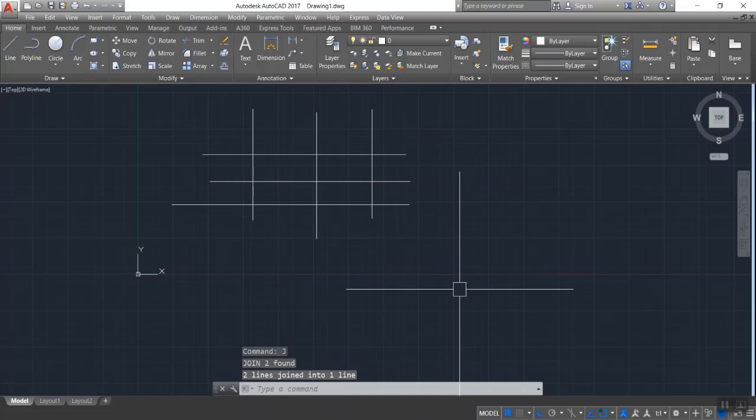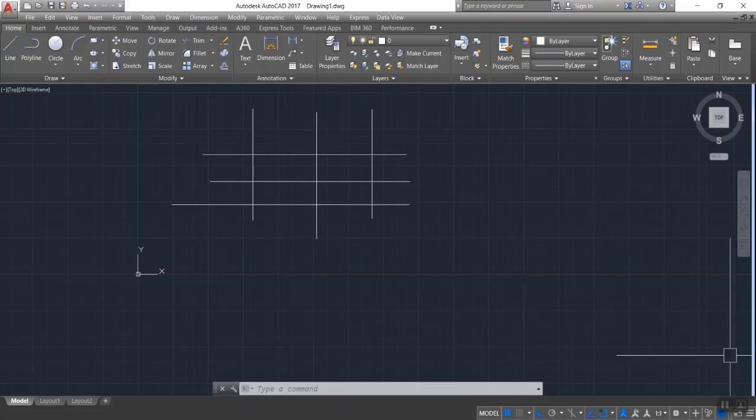It doesn't always have to be trimmed. If there are 2 lines straight, and you need to join them, you can use the command J enter. Alright, this is for today's tutorial. See you in my next class.